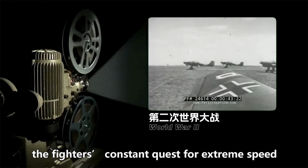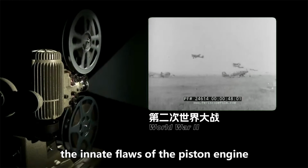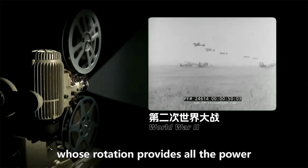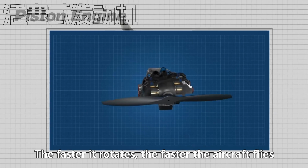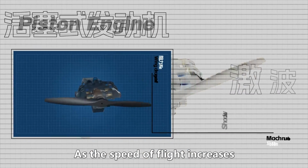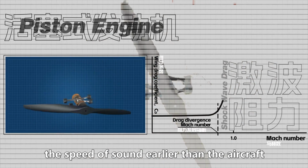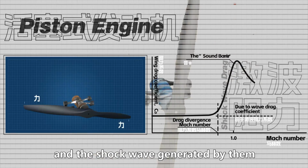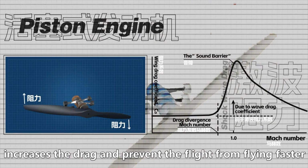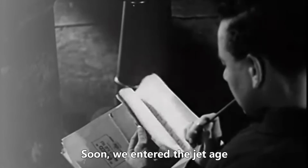However, in World War II, the fighters' constant quest for extreme speed and aerial stalking exposed the innate flaws of the piston engine. It's a propeller whose rotation provides all power. The faster it rotates, the faster the aircraft flies. As speed of flight increases, the propeller tips will reach the speed of sound earlier than the aircraft. The shock wave generated by them increases their drag and prevents the flight from flying faster. A new propulsion model was in urgent demand. So we entered the jet age.